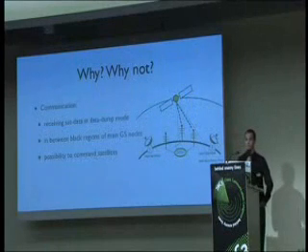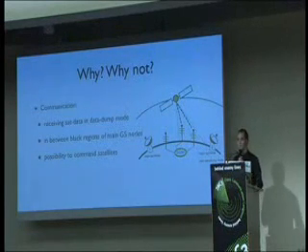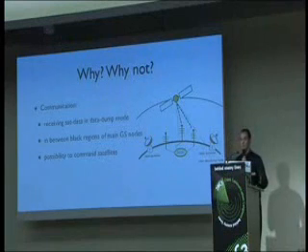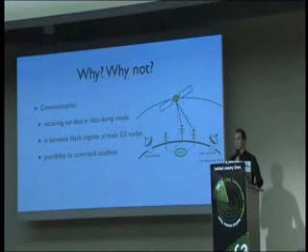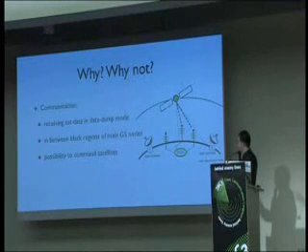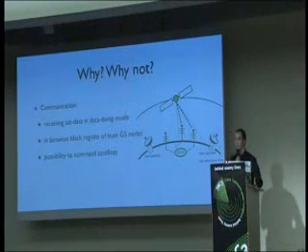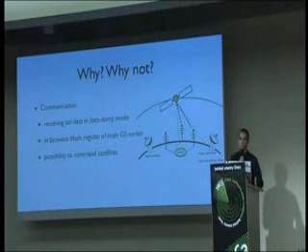Afterwards, when tracking is possible, we also want some kind of communication with the satellites. In this case, it's a so-called data dump mode. We want to get signals from the satellite, like housekeeping data, the temperatures inside, and some other really important data that will be sent down. Then our distributed ground station network could fill in some gaps between the main nodes the satellite owner already rented.